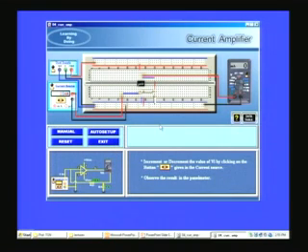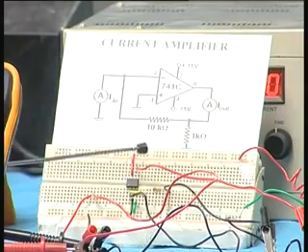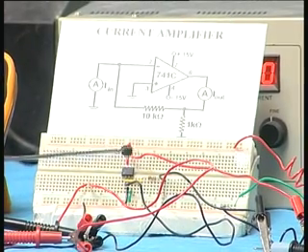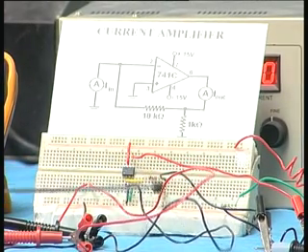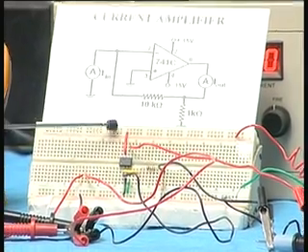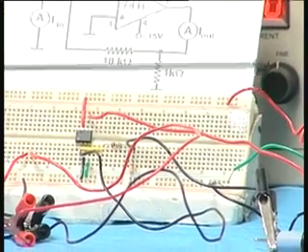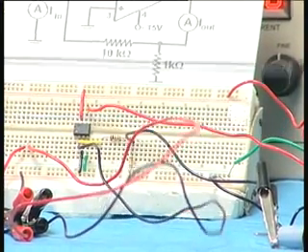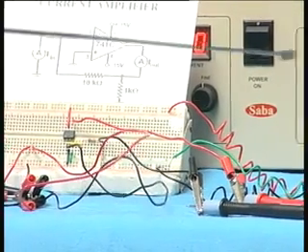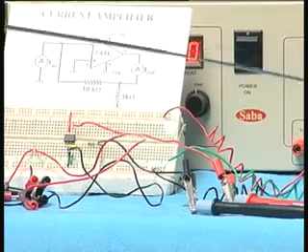Now what we have to do is go and perform this experiment on the experimental table. We will do that. So you can see this is the breadboard on which the circuit has been wired. You have the op amp, you have the feedback loop, you have the two resistors, R1 which is 1K and R2 which is 10K, and the power supply lines are exactly similar to the simulation. This is the plus VCC, the green is the ground, and the black is the ground and green is the negative that is connected here in this place.